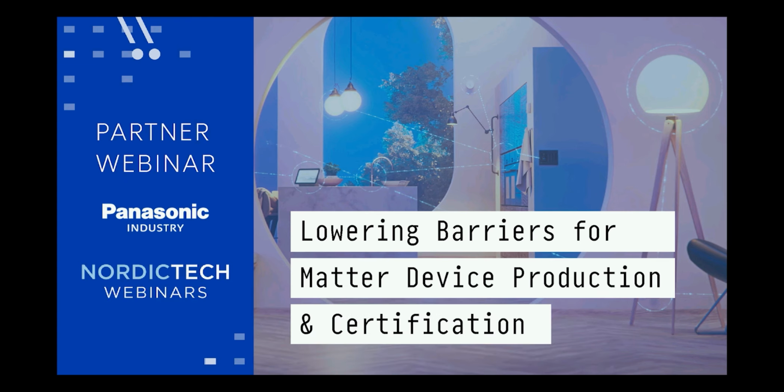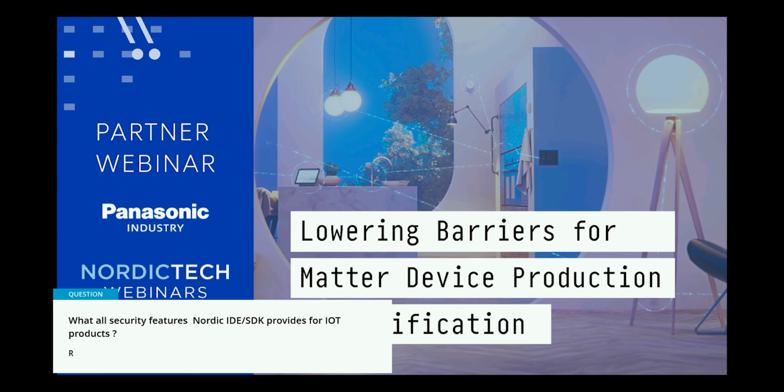So then we have one more question that's a very broad question. What are all the security features that the Nordic SDK provides for IoT products? This is not easily answered in one sentence. The important thing here is probably everything that Matter requires, and more. It also depends on which devices you're using, but in general, the 54L15, for example, has all the features that you would need to get the device PSA Level 3 certified.